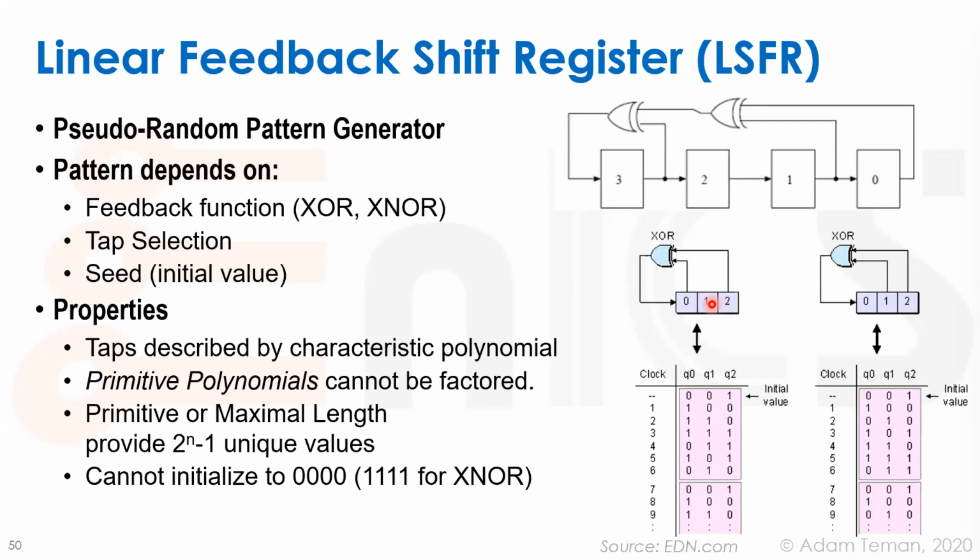it will repeat itself. So it's not really random because it repeats itself deterministically, but it gives something that looks like a random type of generation. So it's really nice to make these kinds of weird patterns, and it's a small piece of hardware. What? Quasi-random. Yeah, pseudo-random they call it. So that's an LFSR, and it's very useful.